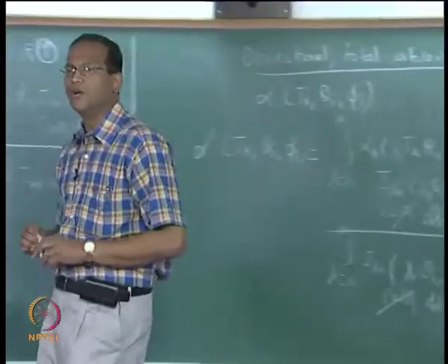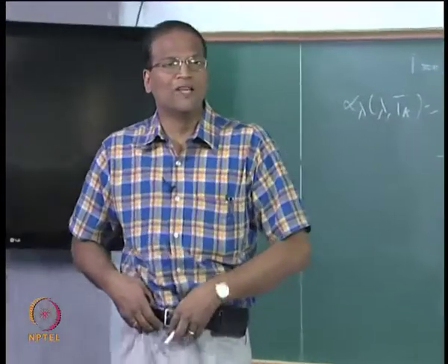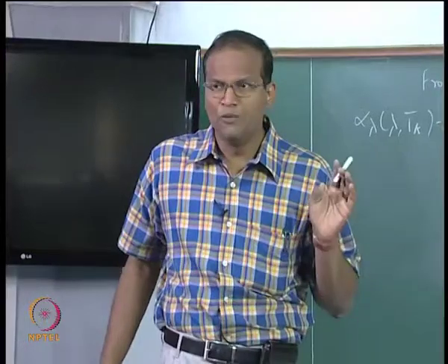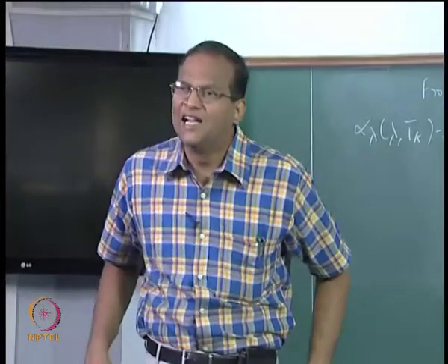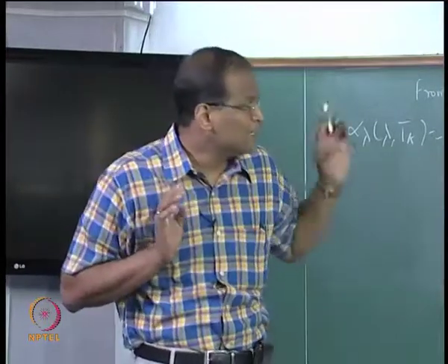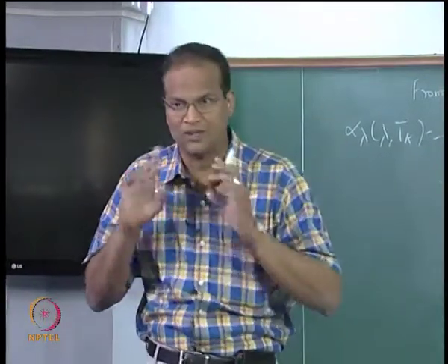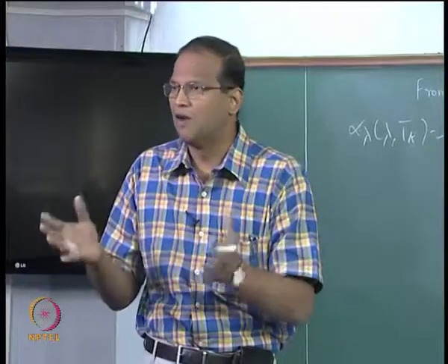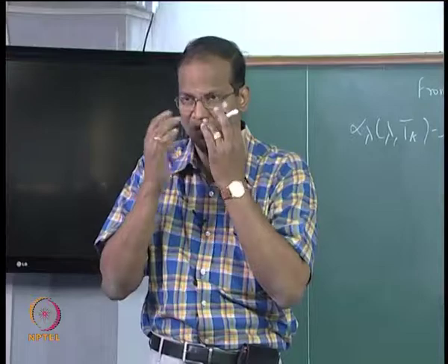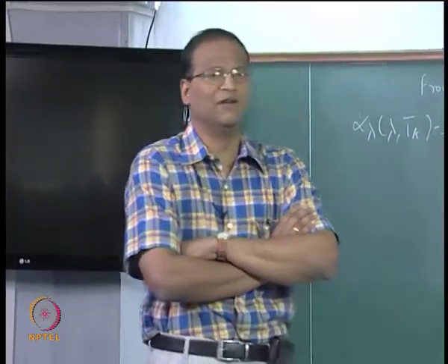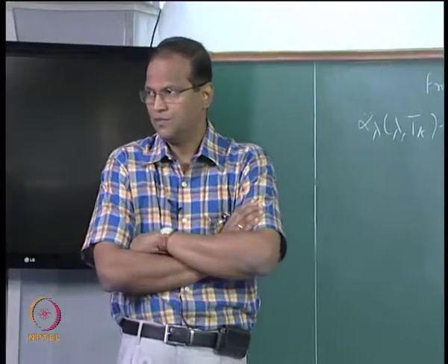To cut a long story short, if alpha lambda dash is given to us, we have a mechanism to calculate alpha. If the distribution is known, you can integrate it analytically or numerically and get it. And this alpha is of final engineering interest to us, because with alpha and emissivity, we will start working on the actual heat transfer problem, which could involve modes other than radiative heat transfer also.